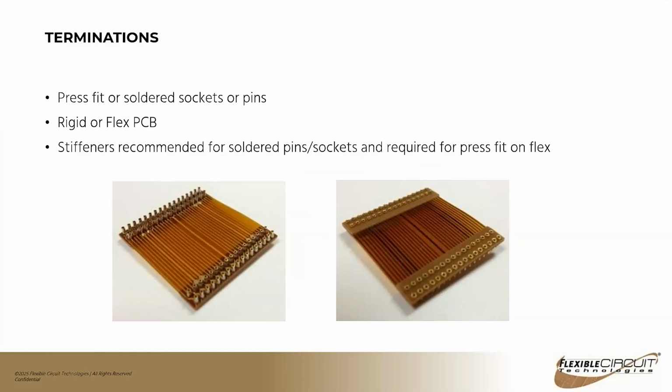So when using this technology in a flex application, typically the press fit occurs in the stiffener material and not the flex material. So your plated through hole or your opening in your pad that we're going to solder to would be slightly larger than the diameter of the pin. So the pin gets press fit into the FR4, extends through the circuit itself, and then solder makes the connection from the pin to the flexible circuit.